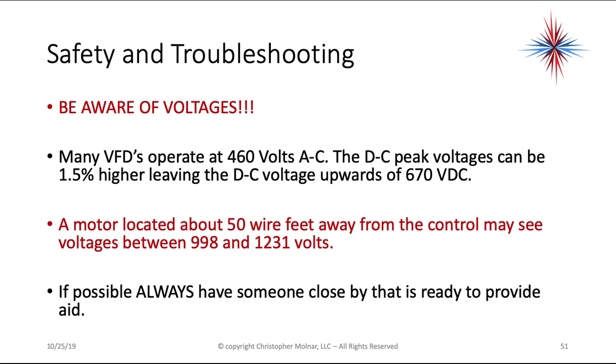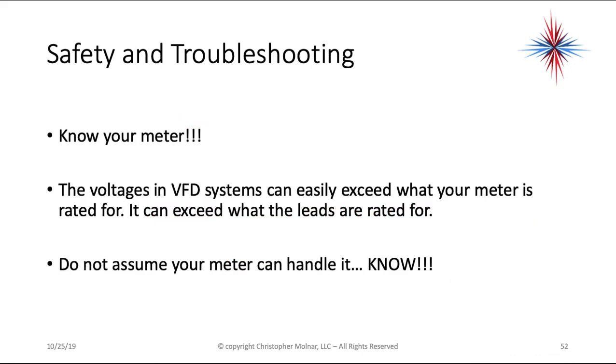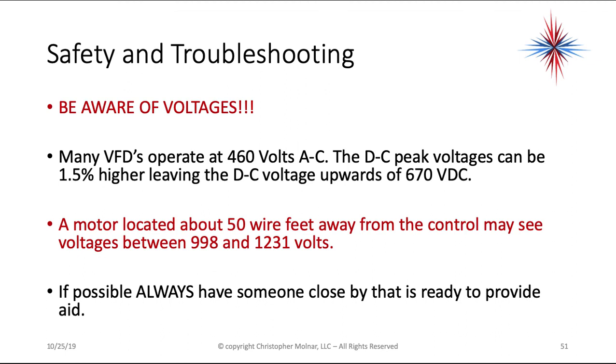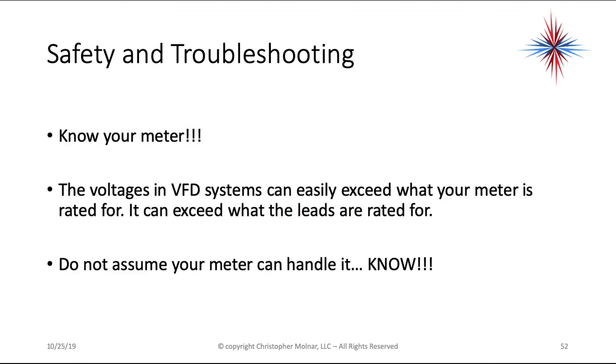If possible, always have someone close by that is ready to provide aid. Try not to check energized VFDs on the motor side unless you have somebody close by, especially if they're energized.